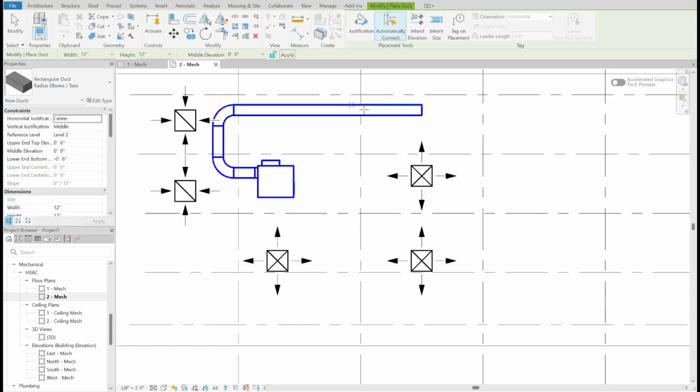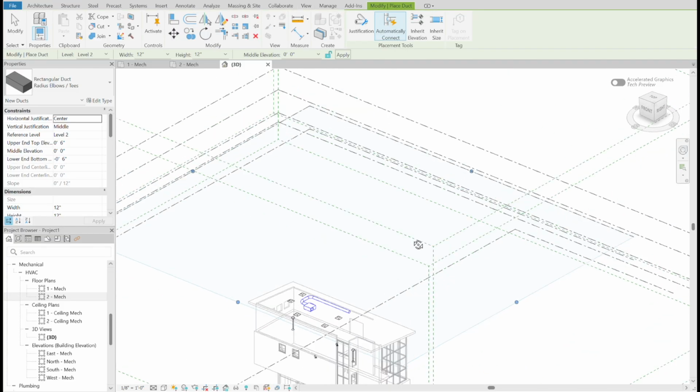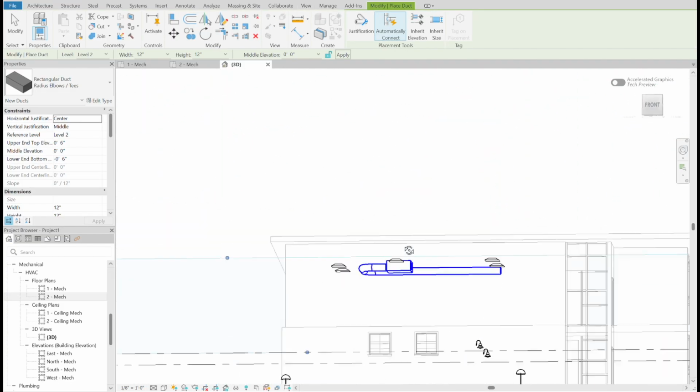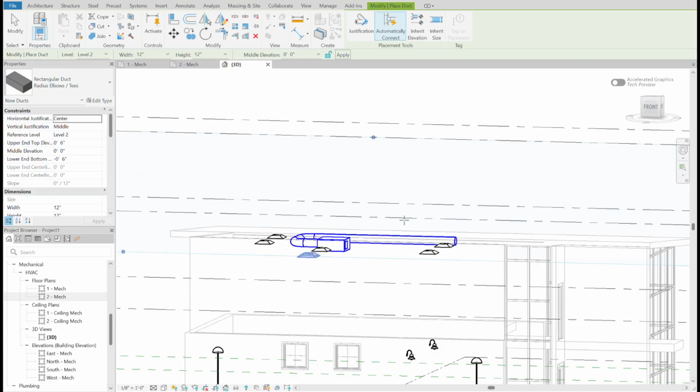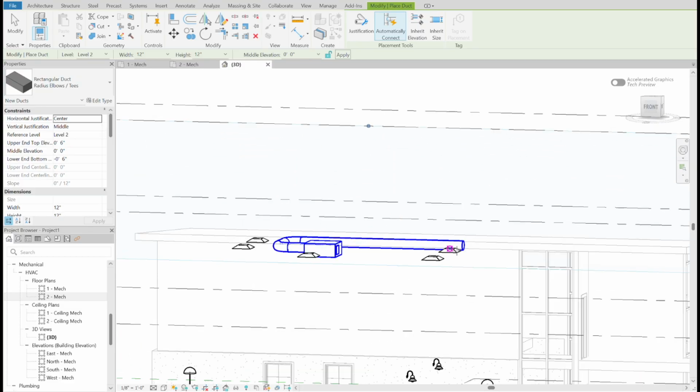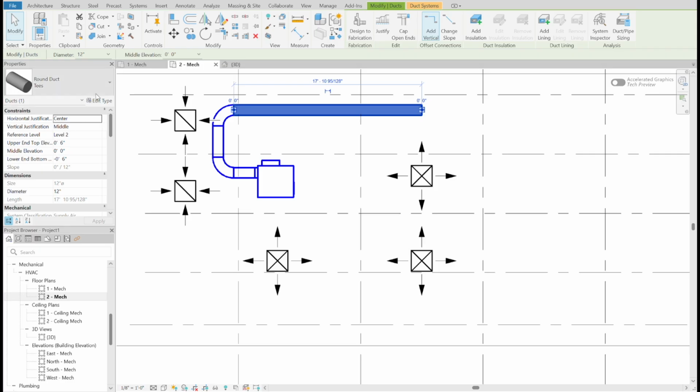It's showing that we don't have enough room to place it. So let's say stop here and take a 3D view of that. I guess the reason is very obvious because we didn't specify any elevation, so there's no room for us to connect to the air terminal. So there are 2 ways of improving that. One way is to basically give it a little bit of elevation, let's say 4.